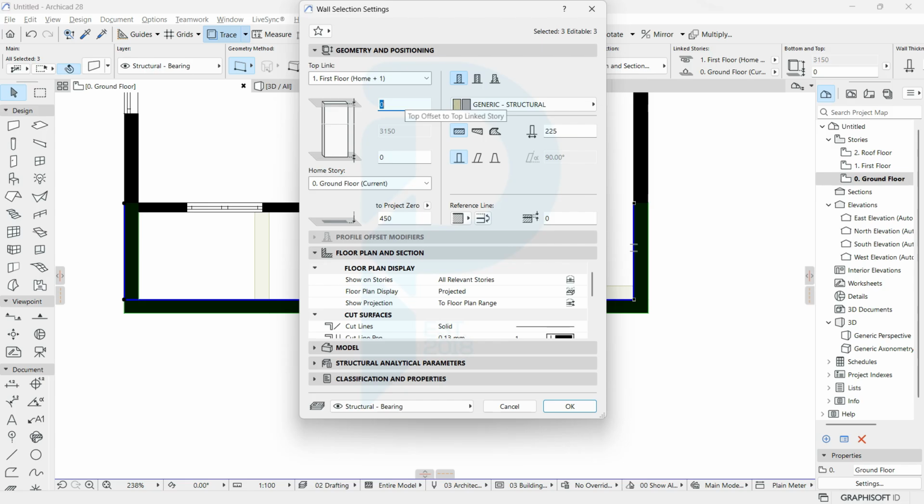If you want to add to an existing wall within a story, you can go ahead and type like a figure 500. If you do that, the height is going to increase. The wall height, you see the wall height has gone up. If you say minus 500, the wall height is going to reduce also. So that's a technique we're going to use. Now, I want to offset the height of the wall down by a factor of minus 300. If I do that, and then I click OK.